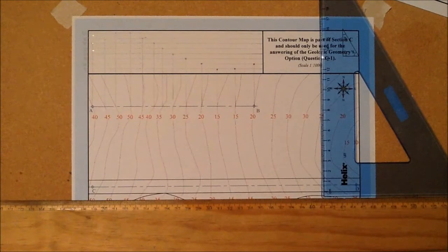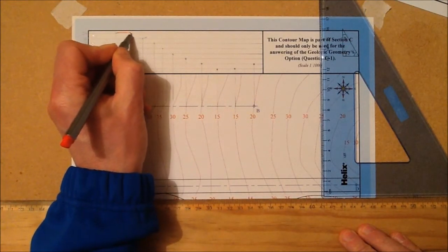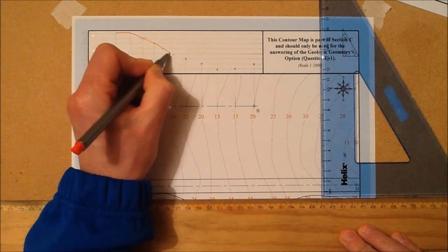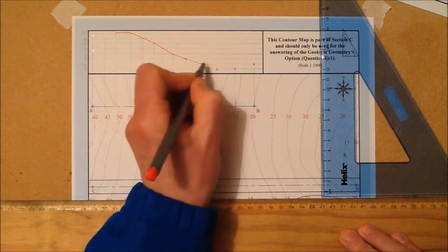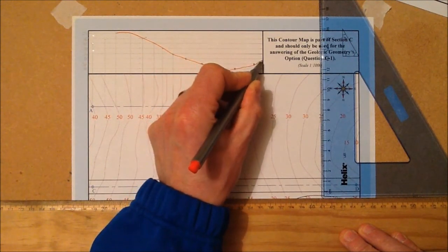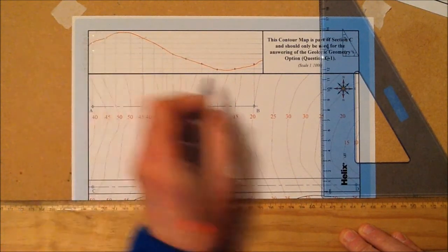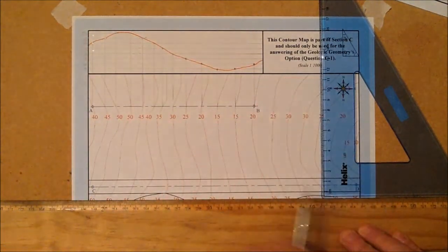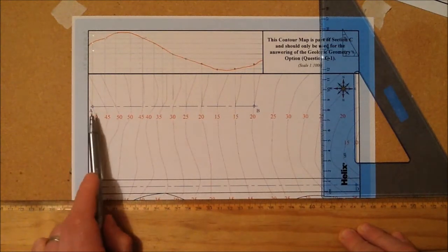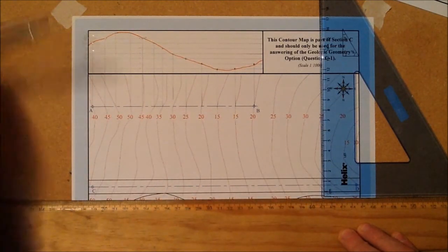So I'm just going to join those points, as you see here. No harm to use coloured pens just to make that more identifiable on the finished drawing. If that line were to extend further onto the land, you would extend it on as you see here in the profile, but because we've been asked just to draw the section through where the line AB is, this will suffice for that question.